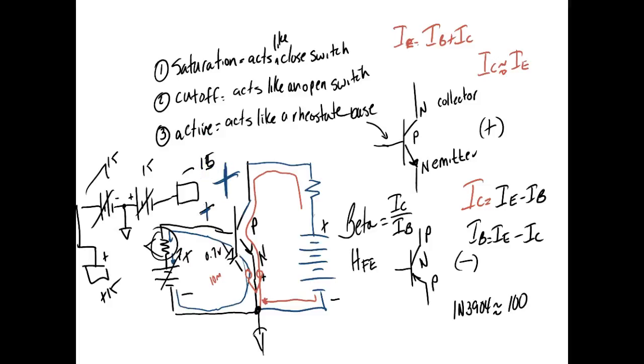So how many volts can I get out of the trainer? Well, I can use one power supply to get a minus 15. If I go across the two, then I can get 30 volts, and then it's up to you to establish the common. What's the difference in potential between a minus and a plus? Well, I'd say 15 minus a minus 15. What are you supposed to do when you subtract negative numbers? Change the sign and add. So that'd give me 30 volts. So on that trainer, if we go across the two power supplies, we can get up to 30.